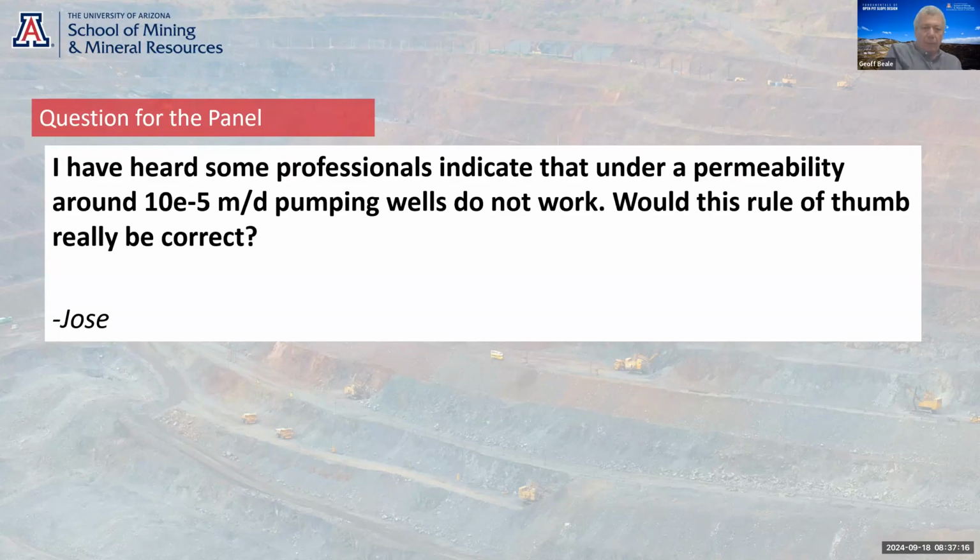And so you're not going to get much out of a pumping well, but it depends what you want the pumping well to do. If you have a mine site where you need to pump, let's say 200-300 liters a second to dewater it, then that permeability is going to give you probably just a couple of liters a second. So that site is not going to be viable. But if you are, for instance, trying to depressurize a clay layer, and you elect that the best way of doing it is a line of closely spaced low flow pumping wells, then getting a liter a second or less may give you what you need.